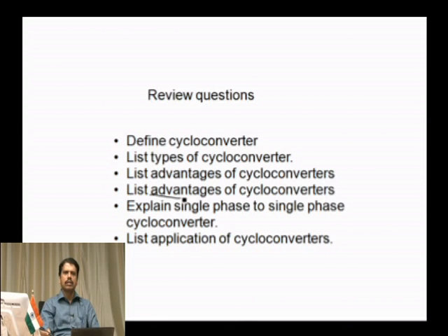In mining, where we use drives, to vary the speed of an AC drive, maybe a synchronous or induction motor, we need a cycloconverter. In the particular application, the frequency required is 7 hertz minimum and 20 hertz maximum, and the speed range was 140 rpm to 400 rpm. To control such very slow speed, very high power rating motors, we invariably go for cycloconverters.